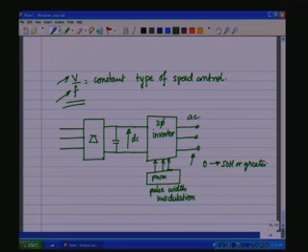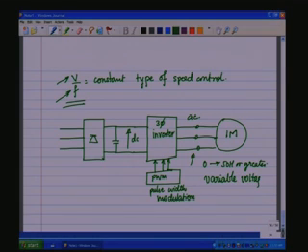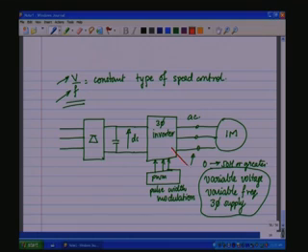The modulating signal. So this will be applied to the induction motor, which can get variable voltage, variable frequency, three-phase supply by means of this inverter, and therefore the frequency can be controlled, and you can have V by F type of speed control, and you can have a whole speed range right from close to 0 up to even over base speed or over 120 F by P.